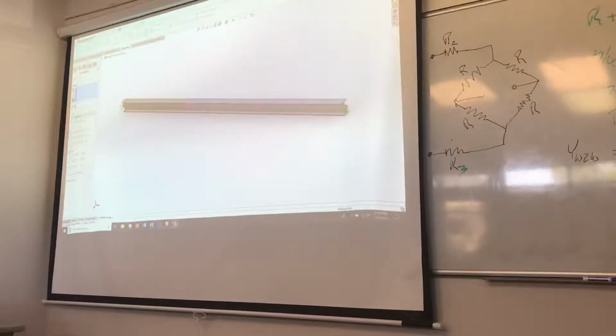I'll have to select beam first over here, so it'll pick a beam. I'll pick that one. I'm gonna pick a reference geometry, the top plane, just so I can put the force out of plane. Looks like it's coming up from the bottom. I want it to go down, and I'm going to make the arrows bigger because they're not big enough.